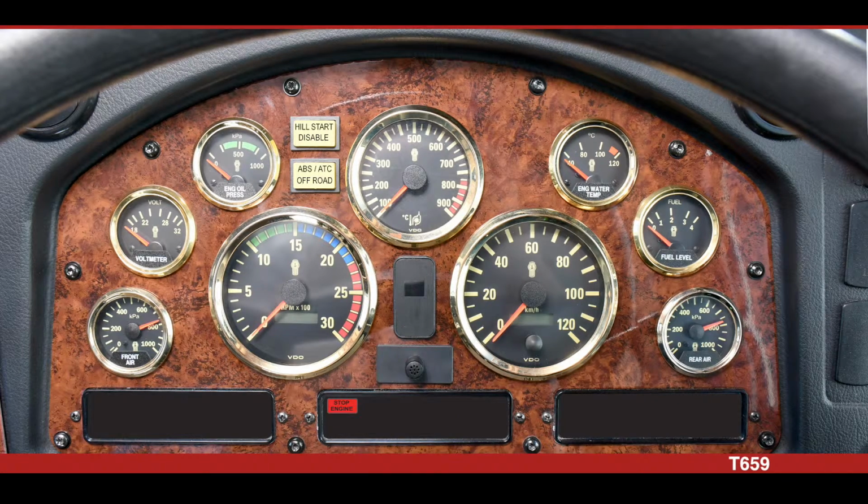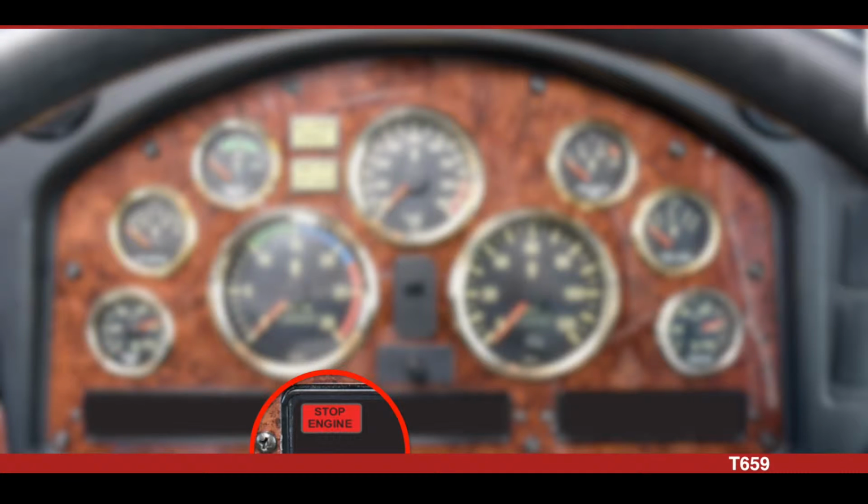The stop engine light. This illuminates when a major engine system problem exists. The driver should stop the vehicle as soon as safely possible and have the fault repaired before driving the vehicle again. This should be considered an emergency. The vehicle must be repaired and the problem corrected before continuing.